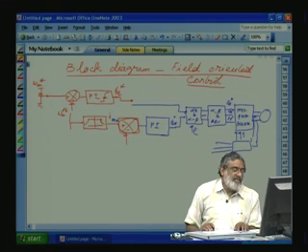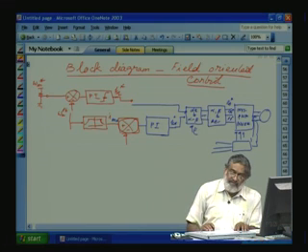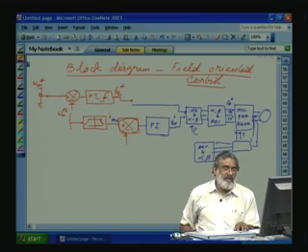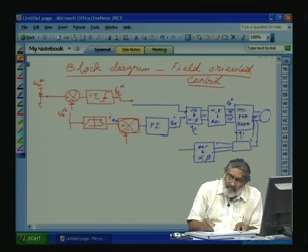Assuming rho is available, this 3-phase current we convert from ABC to alpha beta. Then, since rho is known, we find alpha beta to dq.